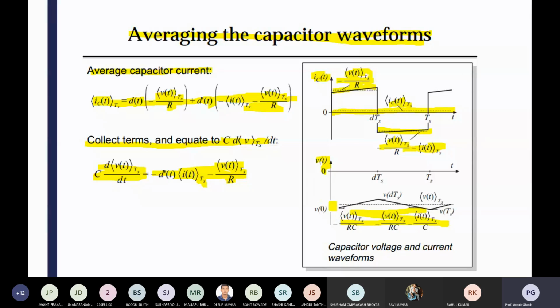Finally, the slope will be there like your inductor current. In the case of inductor current, here we get the expression for the capacitor voltage. Basically, the capacitor voltage is your state variable. In the case of the inductor, the inductor current is the state variable, and in the case of the capacitor, the capacitor voltage is the state variable. A similar method is there for the initial condition: v0 will have some value, then it slopes down and reaches vdts.